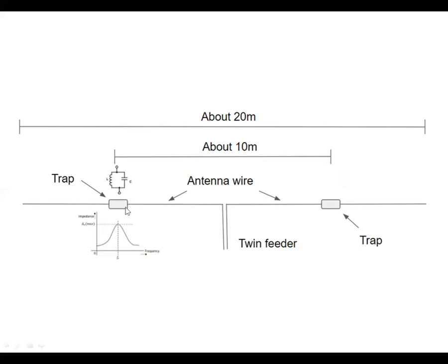So it's kind of a reactance switch that switches the 40-meter part of the element on to the antenna when you get up around 40 meters. So if you're up around 40 meters and both of these are turned on, this thing looks like a 40-meter dipole. So you're getting two bands with one antenna, both 20 meters and 40 meters.